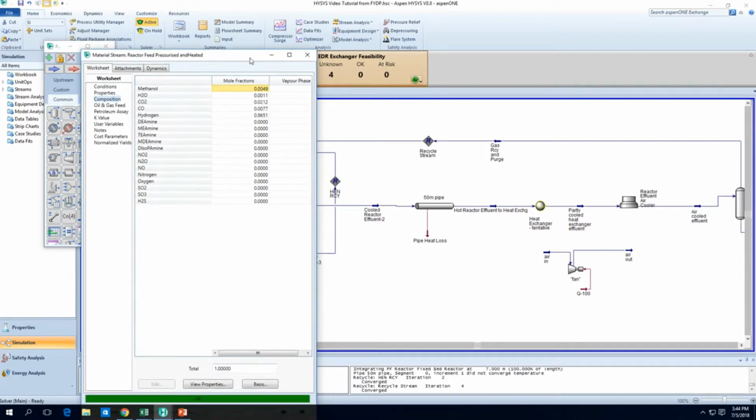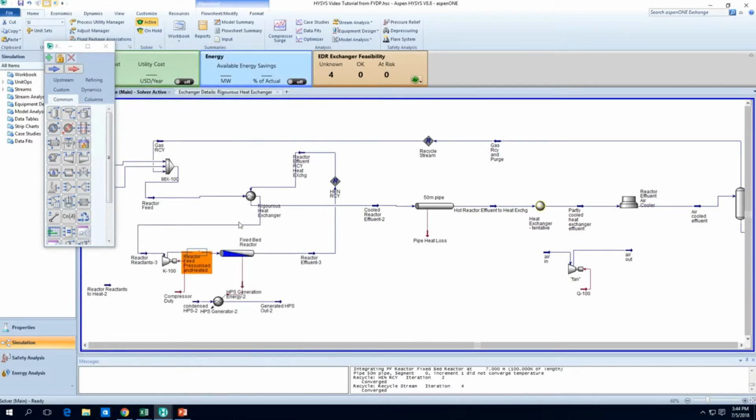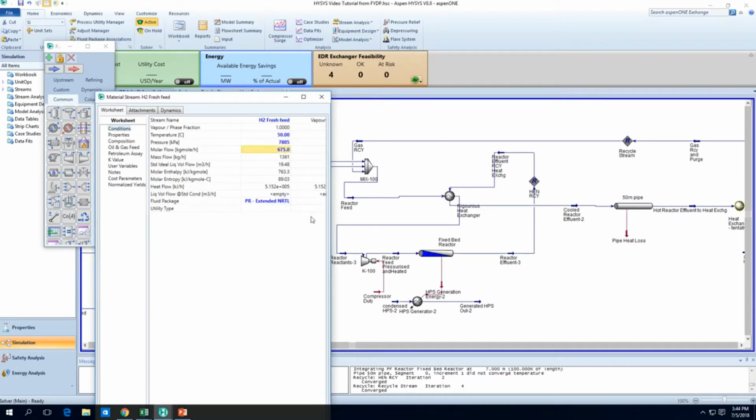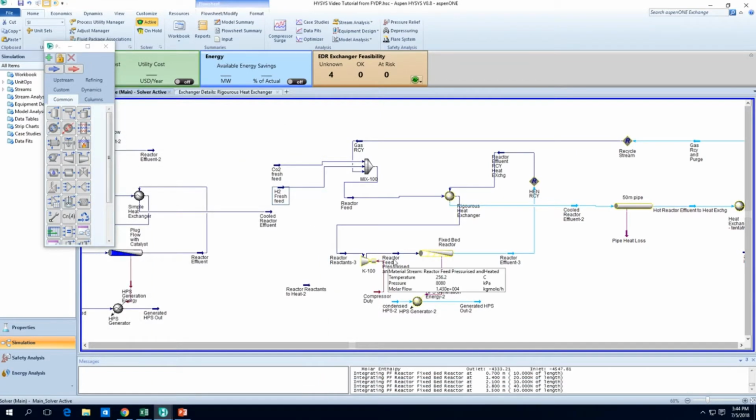Okay, and we want this CO2 composition to be around 17%, where according to the research paper, it will be optimal around there. So we'll need to reduce the hydrogen concentration a lot. So what we do first, we remember that we need to set our molar flow rate at about 675. That's the steady state value. So I'm just going to put it at 0 first and let it iterate a few times. So you can see this molar flow here is going to start dropping a lot.